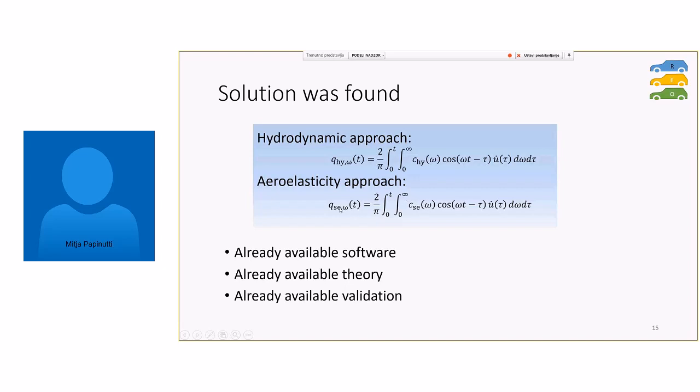Now, as you might see here on the left side, I haven't written all the equations. This is not the total solution. This is just the solution for the frequency dependent part. So in hydrodynamics you're simulating the frequency dependent part, and in aeroelasticity we are also just using the frequency dependent part. The part that is not frequency dependent, because we also have infinite contributions, we can solve analytically by simply adding a matrix term into Newmark.